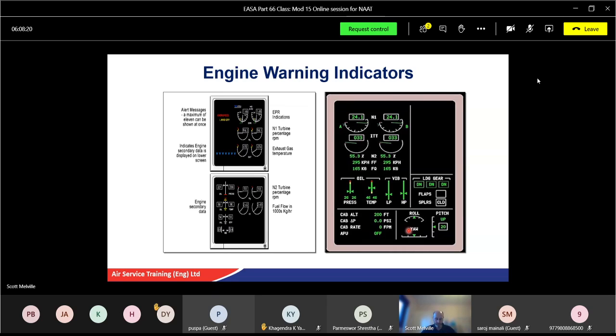And also, is the impeller proportional to the fuel mass flow rate as well? Right, with a vane type flow meter, the chamber in the vane type flow meter, when the vane looks like a rudder on a boat, is it directly proportional to flow rate or indirectly proportional? Directly proportional. Yeah, in the book it calls it linear proportional, so directly proportional.